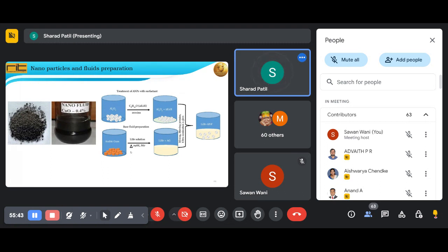and one can get the improvement in the characteristics of whatever the fluid is. So the major characteristic we are getting is the improvement in the conductivity. And the hypothesis says that if the conductivity is improved, automatically, Q is equal to minus k dT by dx, or if you have conduction plus convection, that is the advection effect, then automatically you will get the improvement in the heat transfer.